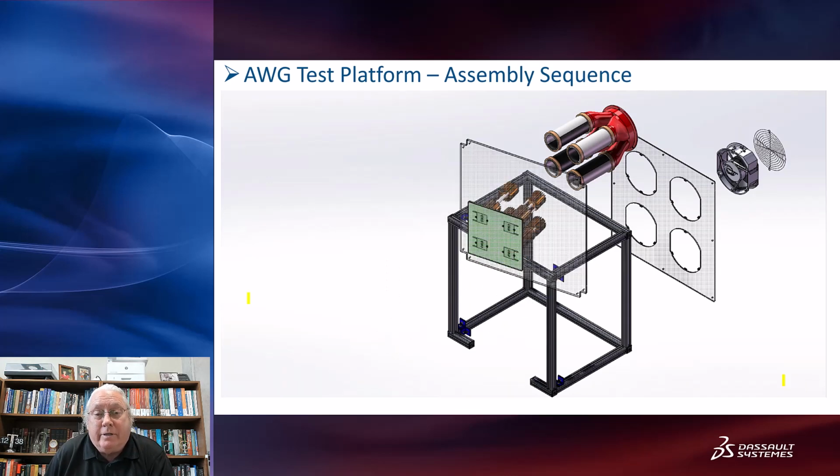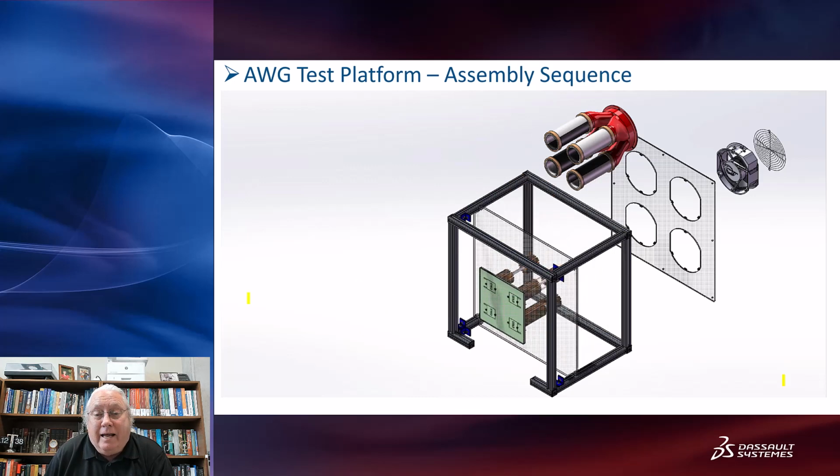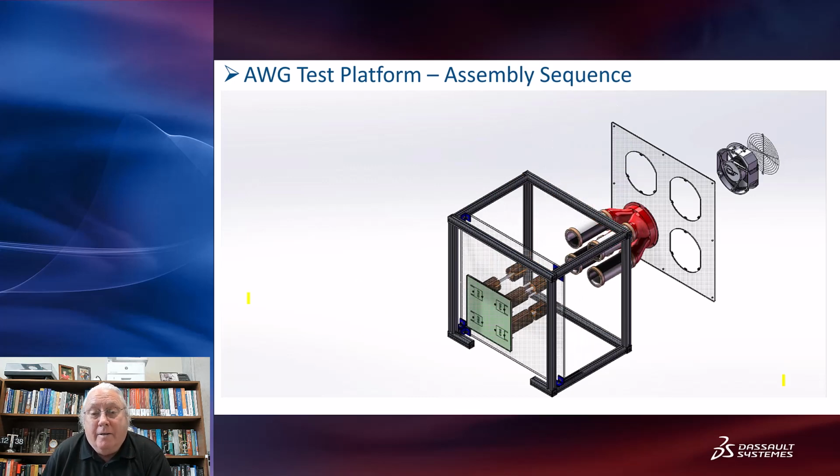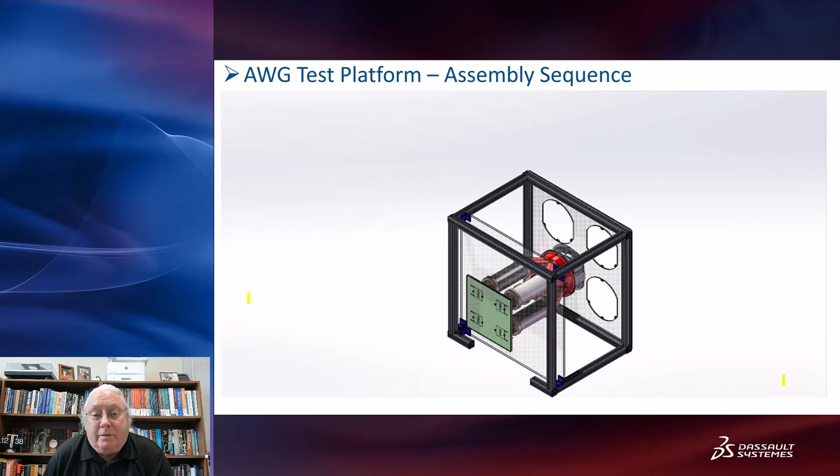The Peltier device is on the other side of the hot plate, and there's foam around to isolate the thermoelectric cooler so the heat doesn't get into the other part of the system. And so on the near side, there's a cold side of the Peltier device. On the far side is the hot side, and those quarter-size condensation plates are going to be on the cold side, and that's what gets cold. And then we're extracting the heat by blowing air across these heat sinks and these heat pipes, that we'll see here in a minute, to try to cool the hot side.